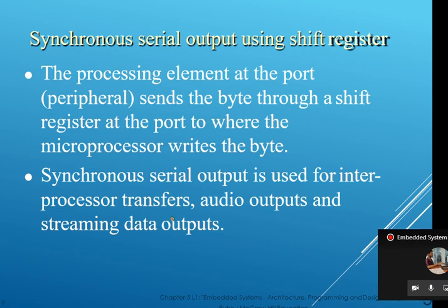I don't know whether you people are imagining or not. So this is one flip-flop, and here one more block. So I will draw 4-bit inputs. So how is it sending the data serially? It will be only one data in and one data out. And here I will give the clock pulse.